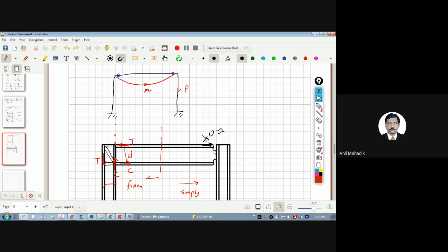And we are only connecting this beam to the column through the web only. That means we are only transferring the force which is shear. So shear is transferred directly here. That reaction is transferred through this bolted or welded connection through the web only. So I'm not connecting this flange to the column. So this is your simply supported connection. I hope you got the concept.